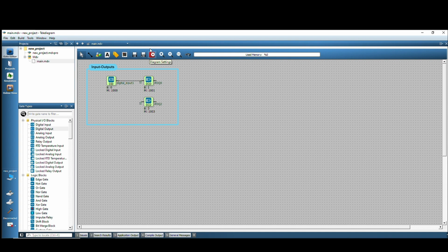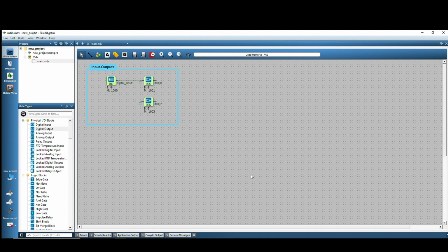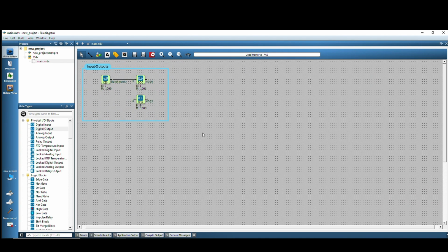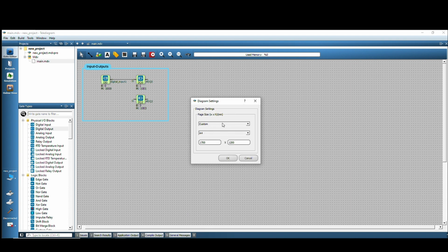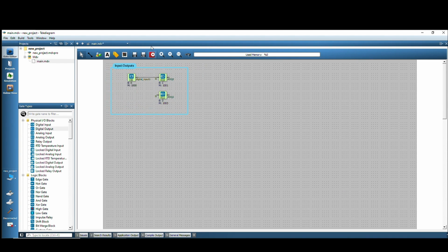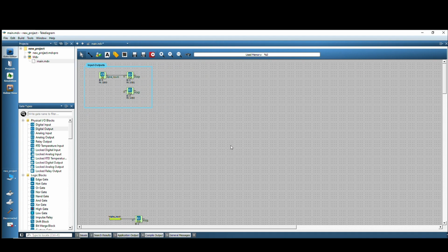The next setting is the Diagram Settings icon. In diagram settings, as seen currently, we can observe the page size. When I hold down the control and move with the mouse wheel, I can observe the page size from here. When I click on diagram settings, a page structure of 1600 by 2500 is set. If you want, I can change it to different sizes, as seen. Or if you define it yourself, 2500 by 3700. That is, you can expand in the diagram settings section when the area on your